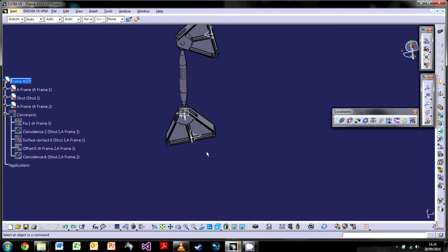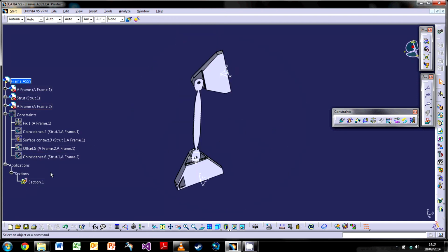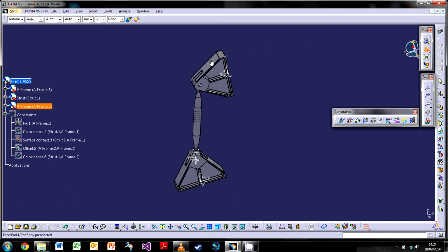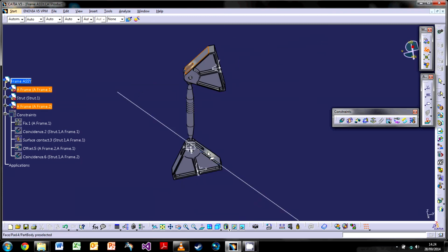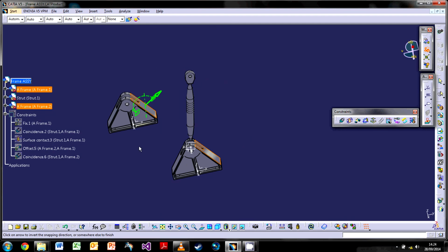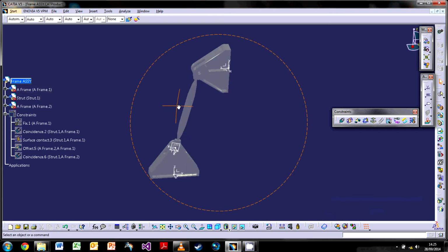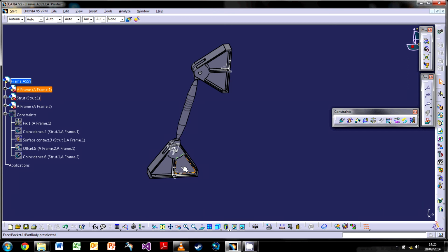So press Ctrl Z, get it back. Oh, hello. But it works as well for surfaces, so I can connect that surface and snap it to that one there. Again, you get this sort of immediate snapping feature. Of course, because it's been constrained, as soon as I click update, it'll pop straight back there. But if you have a CGR or some other file which isn't a CATPart, the snap tool is what you'll want to be using.